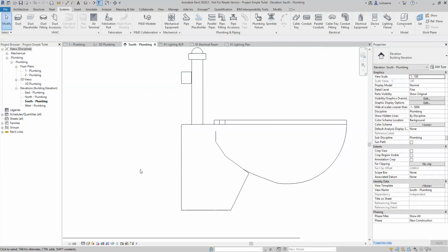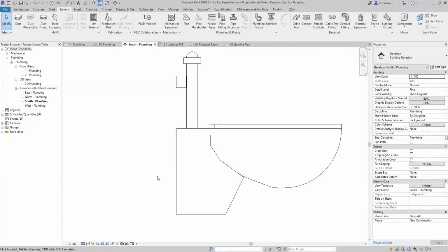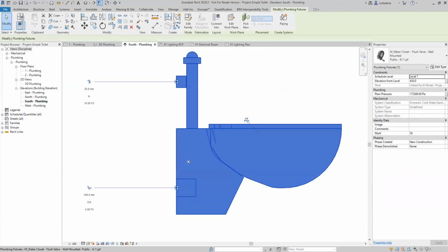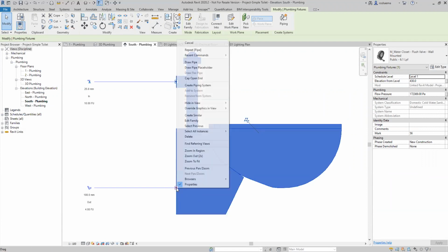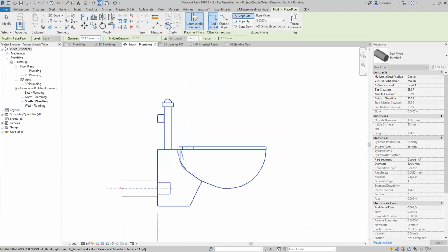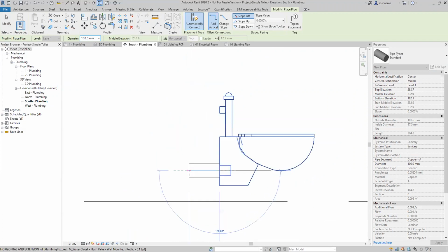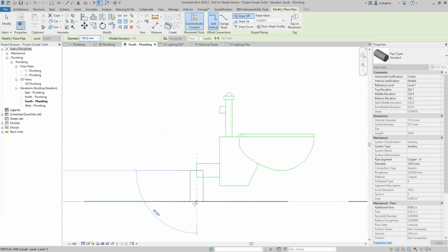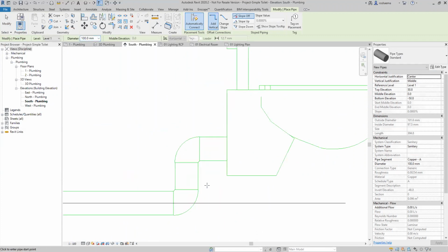And another way to create a pipe, and this is a much easier way, we just click to activate it and it will show the connectors. Okay, you just hover your mouse at the point and then you right click it. You can see here, Draw Pipe. So you can just draw pipe. This one is much better actually because it will automatically give you the right size for you. Okay, so I'm just going to click 1, 2, and 3. Just as easy as that.